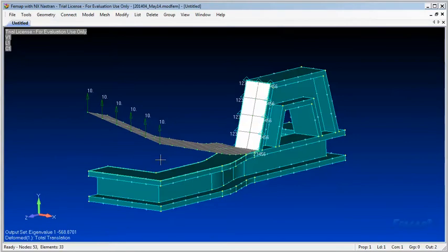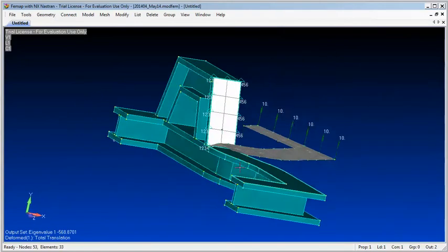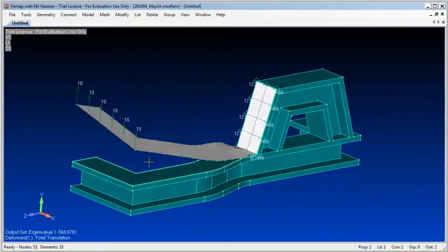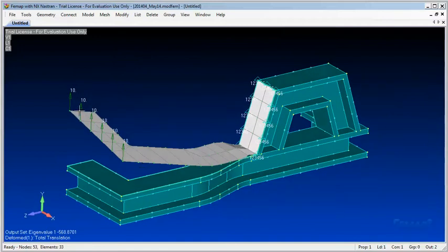So you see what happened here to the surface, the edge that the load was applied. So the eigenvalue: the model buckles at a load of minus 568.87 times higher than the applied load.